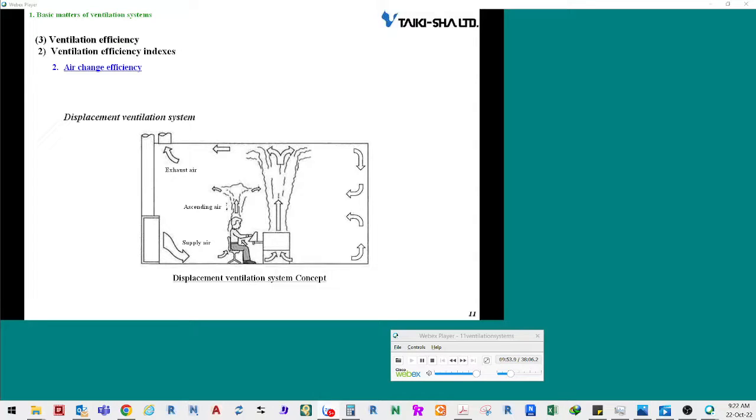Dust and gas generated by pollution sources are carried towards the ceiling by using the power generated by this current of air. The displacement ventilation system is intended to maintain the environment of residence areas by exhausting the air from the height of the ceiling. Theoretically, the displacement ventilation system is more similar to the system using a piston flow rather than the system using completely mixed air. Higher ventilation efficiency, therefore, is provided.